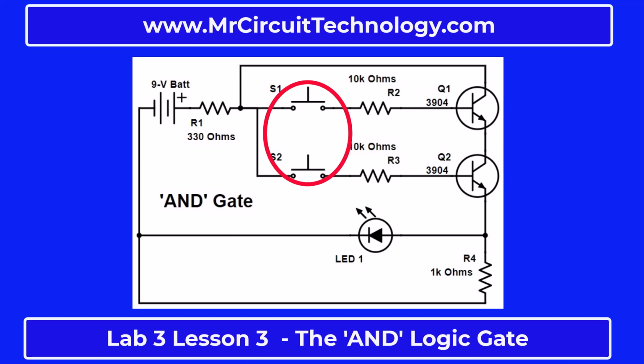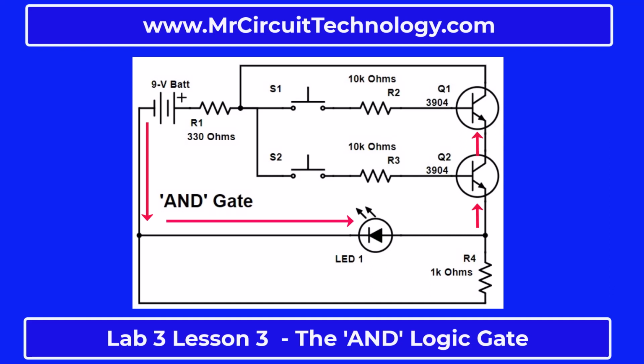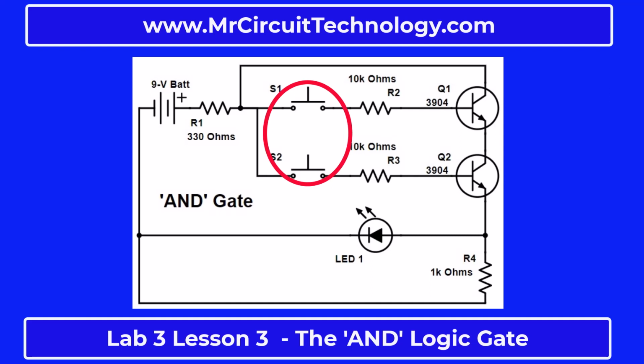When both switches are pressed, the path for the current is from the negative of the battery through the LED, then through transistor Q2 and Q1, then through resistor R1 and back to the positive of the battery. If you do not press any switch, or if you only press one switch at a time, the LED will not light up, which indicates a false on the output of the circuit. So as you can see from this explanation, this circuit works like an AND digital logic gate. Only when both inputs are true will the output be true. That is to say, only when you put a voltage on the input of both transistors at the same time will the LED light up.